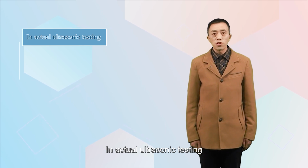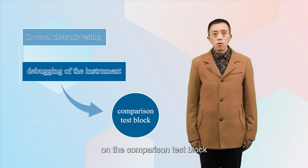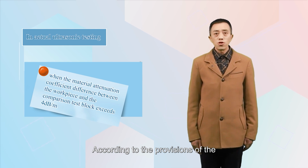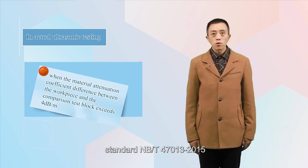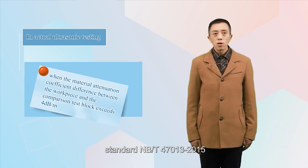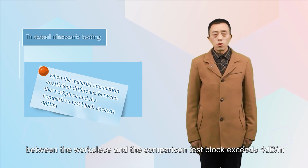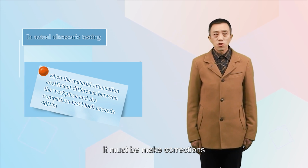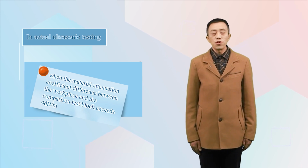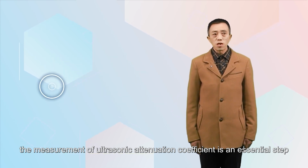In actual ultrasonic testing, the debugging of the instrument is often carried out on the comparison test block. According to the provisions of the standard NB/T 47013-2015, when the material attenuation coefficient difference between the workpiece and the comparison test block exceeds 4 dB/m, corrections must be made. Therefore, the measurement of the ultrasonic attenuation coefficient is an essential step.